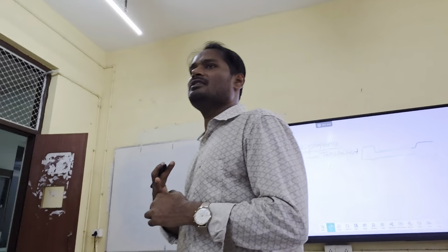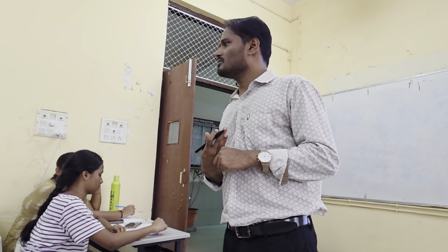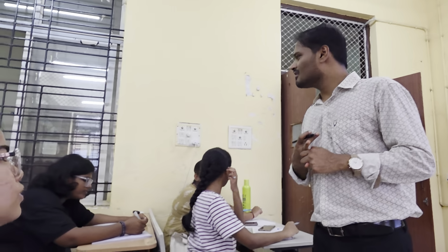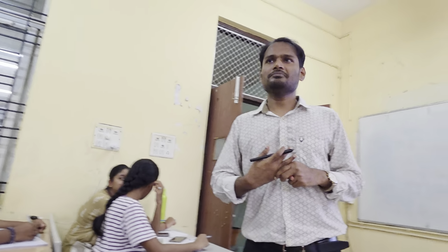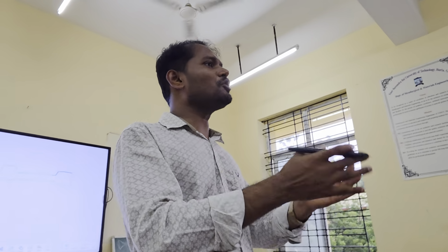So what is the formula? Anybody remember from the physical metallurgy class? Formula for percentage elongation. Yeah, okay. Final length minus initial length divided by initial length. That is called percentage elongation. If you can find it out, you can tell the ductility of the material. If it is very high, it is more ductile. If it is less, it is less ductile. Okay, fine.